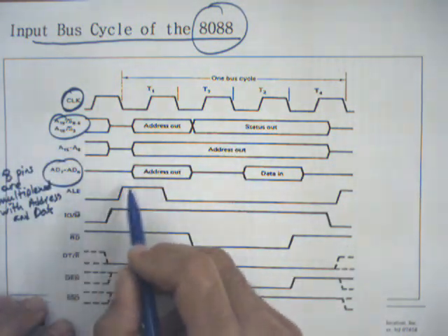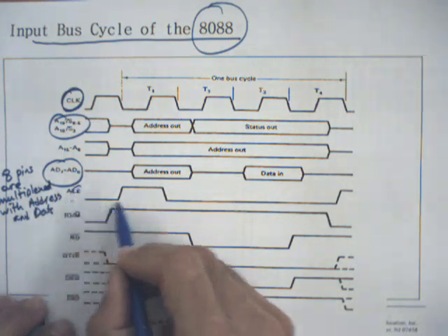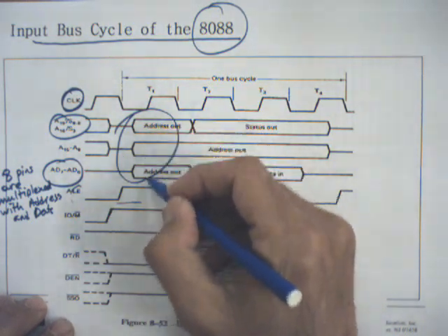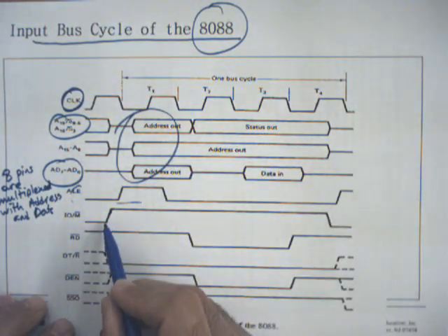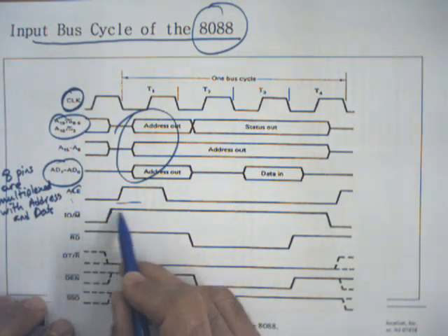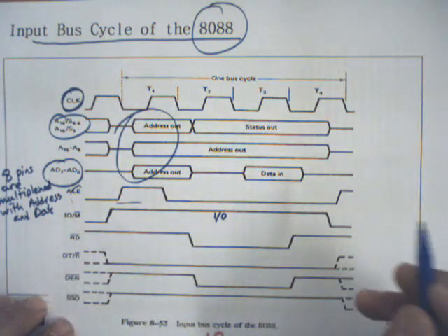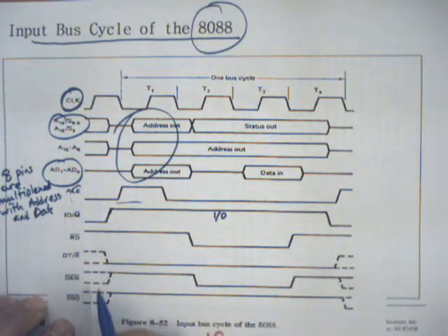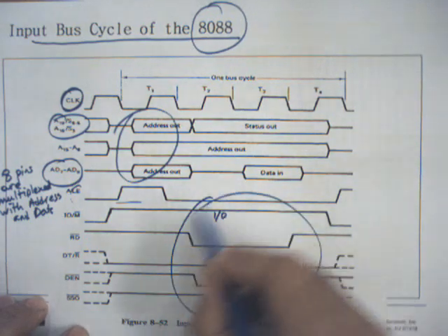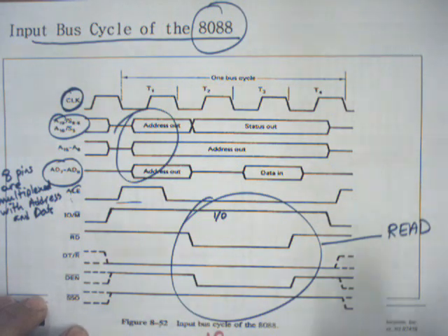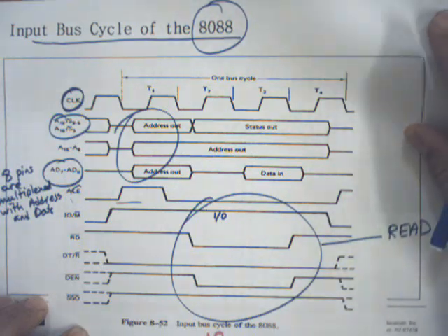And we start by setting the address. First, address latch enable. So the information at the address lines is latched. Then input/output memory is set to high for I/O. If it were 0, then it's memory. So it's a read cycle. Then other controls, data transmit, read, enable, etc. can be activated. So this is a read sequence, input. So information in the bus is read into the microprocessor.